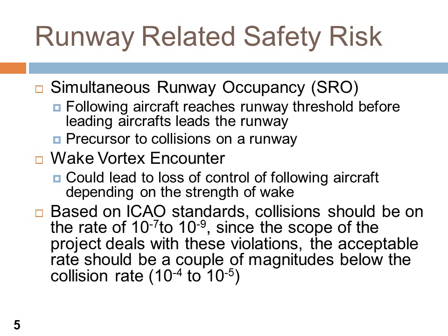So far we've proposed the idea of reducing separation distances between aircraft in order to increase capacity, but with this comes a related safety risk. As aircraft approach and land, two safety violations could occur, a simultaneous runway occupancy violation or a wake vortex encounter. An SRO violation occurs when two planes are on the runway at the same time, and a wake vortex violation occurs when two planes are separated by less distance than the FAA requires.